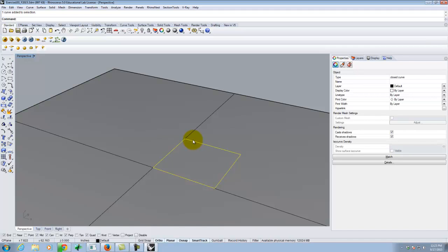Okay. All right. So I have a rectangle corner to corner. The next thing that I'm going to do is create a rectangular plane. So I'm going to come to this surface. Do you see the surface with it? See how it's kind of blue, with 4 dots on the corner? That's a surface from 4 corner points. It's not the right one that I want, so I'm going to click and hold, and I'm going to pick this one, which is called vertical plane. So it's down and over 3.